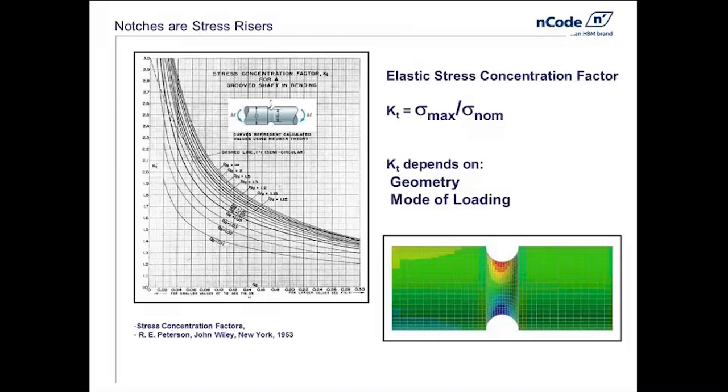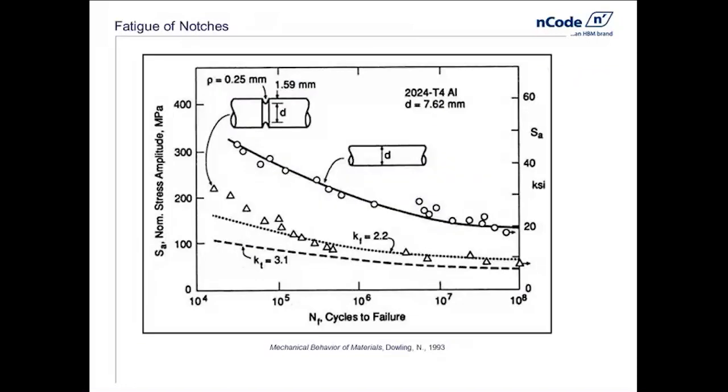The issue is, with certain materials, the levels of stress that we see, these elastic stress concentrations, don't match their performance in fatigue. This is especially true of metals that are cast. Things like gray cast iron you find, or ductile iron you find in a powertrain application in terms of block or crank, tend to be quite notch insensitive.